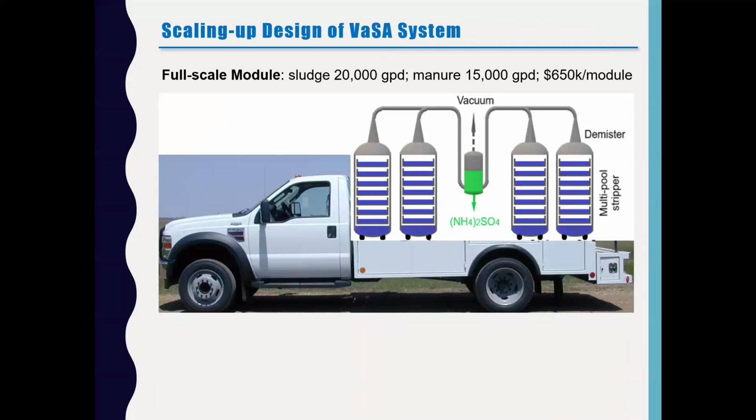So for scale up, we can't just load 15 to 20 centimeters. Our solution for full-scale application is to have a tall stripper. We can mount 9 tanks vertically. Each tank can be fed to the optimum feed depth. But all the tanks share fewer strippers. 4 strippers can share one vacuum system, one absorption system. That's our vision for full-scale design.